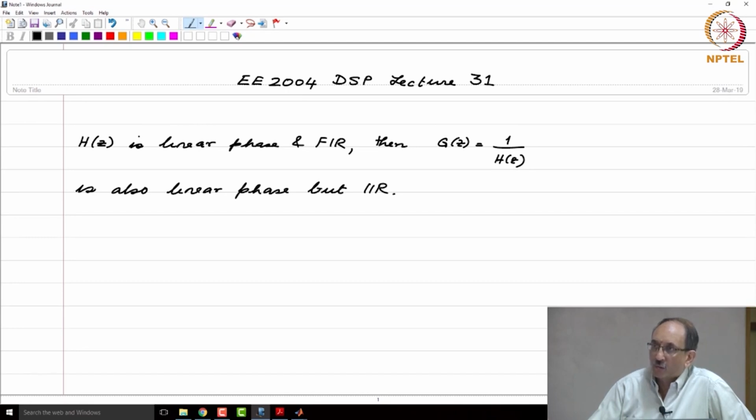Therefore, you now have poles both inside and outside the unit circle at their reflected positions. So, what is the problem then? It can be made stable if you have the region of convergence being the annular region between the smallest radius pole outside the unit circle and the largest radius pole inside the unit circle.